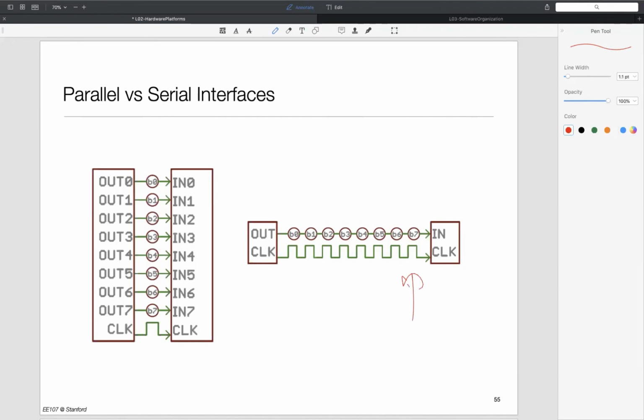Okay. And the reason precisely is, if I were to send these bits, even tiny differences in the length of the wires or mismatches in capacitance values could mean that at very high rate, I may be sending the bits out simultaneously, but they don't arrive simultaneously out here. So I may be sampling some bits of one symbol and some bits from the next symbol, for example. So that can create utter chaos. So high rate links tend to be serial. If you are doing parallel, particularly over cables, it's pretty hard to get them right.